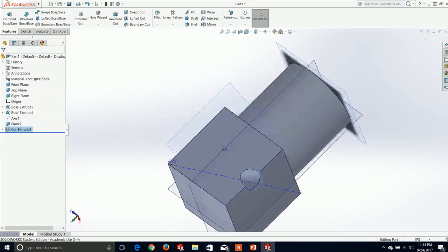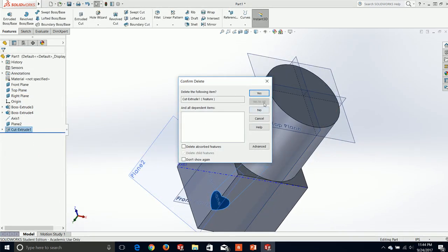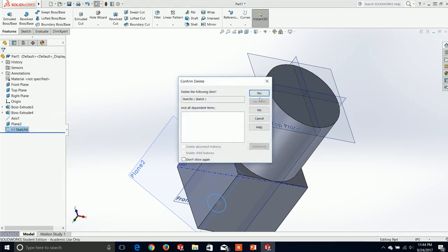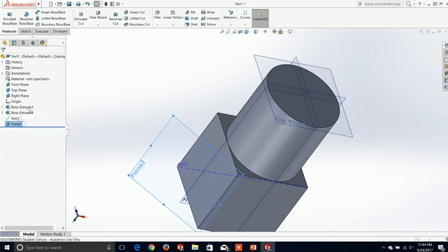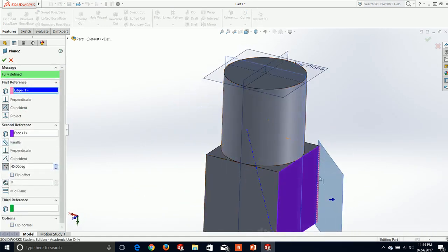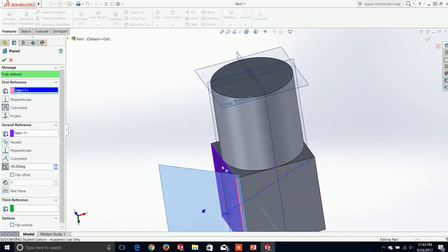Just like that. So let's go over what we had to do to create that plane. I had to give it an axis of revolution. I could have made an axis itself, but this edge served me just fine. And I also have to give it a reference surface to which to measure the angle right here.